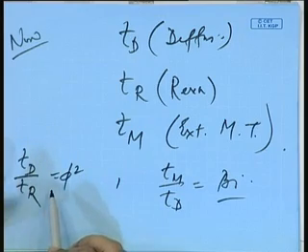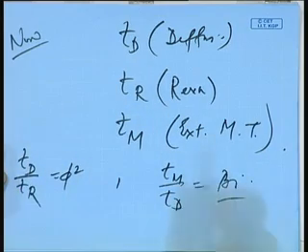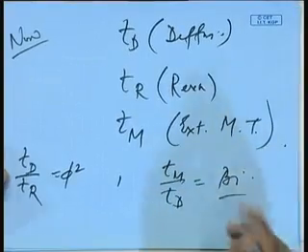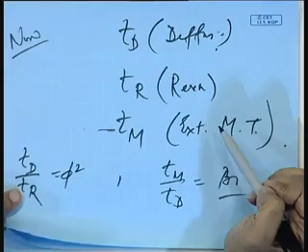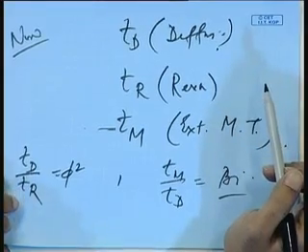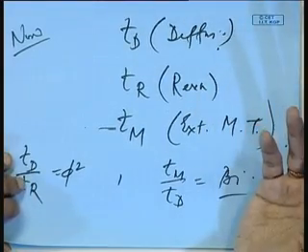One is the ratio of the diffusion time to reaction time, phi square, and another one is the ratio of mass transfers. Here, for example, this is an external mass transfer and diffusion is internal mass transfer. So, you have another number, which is the ratio of external to internal mass transfer. In addition, you can form another number actually, because you have surface reaction, and the rate for surface reaction is going to be different from the rate of the reaction inside the matrix. Why is that? Because inside the matrix it is a volume average rate, whereas the surface reaction rate is the intrinsic rate based on the surface. So, you can form another number there. We are not going there, but there is a possibility.